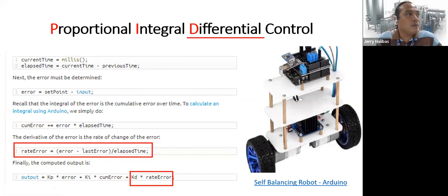Then, if you want, you can use a Bluetooth connection between your cellphone and the robot, so that your robot responds depending on the acceleration or velocity from the accelerometer or inertia sensor of your phone. You can just tilt your phone forward and the robot will respond. You can add that by using Bluetooth. Try to access the accelerometer or inertia sensor on your phone for additional features for your robot.